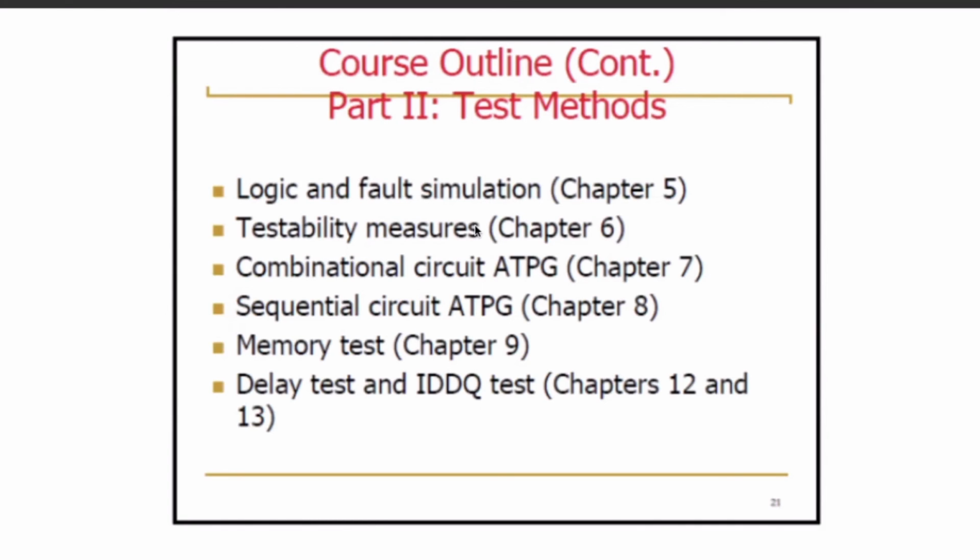And there is also multiple software, like in Synopsys for logic and fault simulation and ATPG we have the TetraMAX tool, and in certain iterations we can do the test generation, and we can also select the methodologies they have deployed in the tool, and we can see the patterns for this design. What are the patterns and how much will be the fault coverage? We can see these things practically on that tool, the TetraMAX tool.